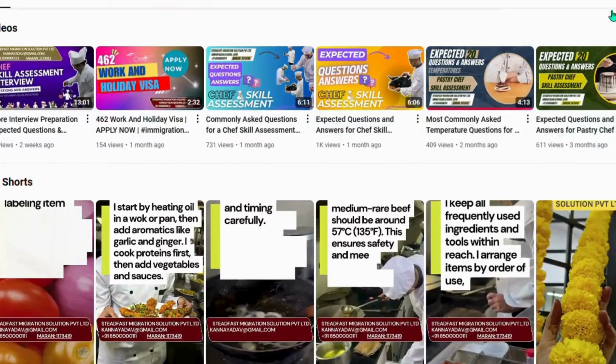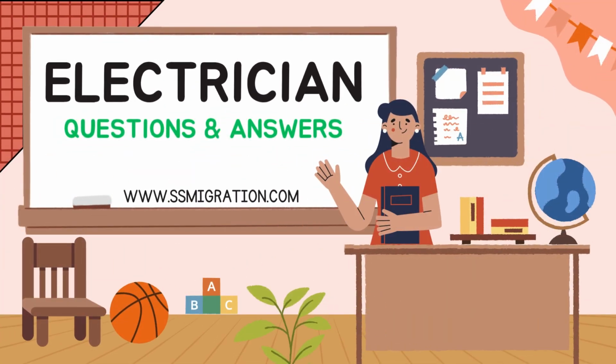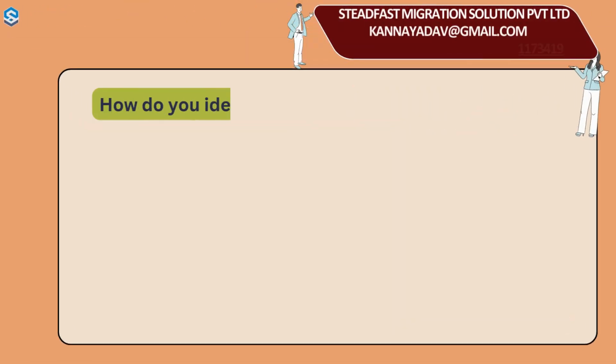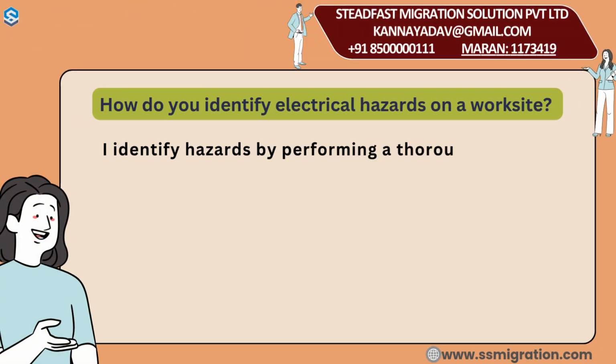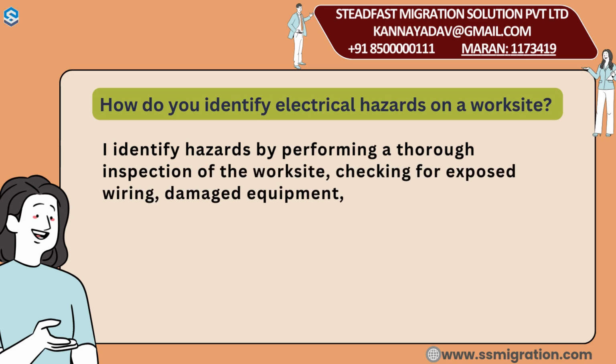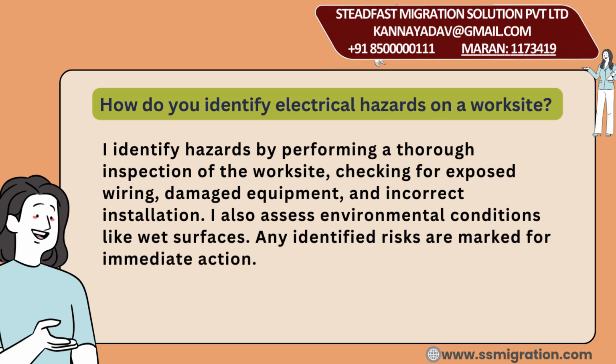In this video, we'll cover important electrician questions and answers to help you ace your skill assessment. How do you identify electrical hazards on a worksite? I identify hazards by performing a thorough inspection of the worksite, checking for exposed wiring, damaged equipment, and incorrect installation. I also assess environmental conditions like wet surfaces. Any identified risks are marked for immediate action.